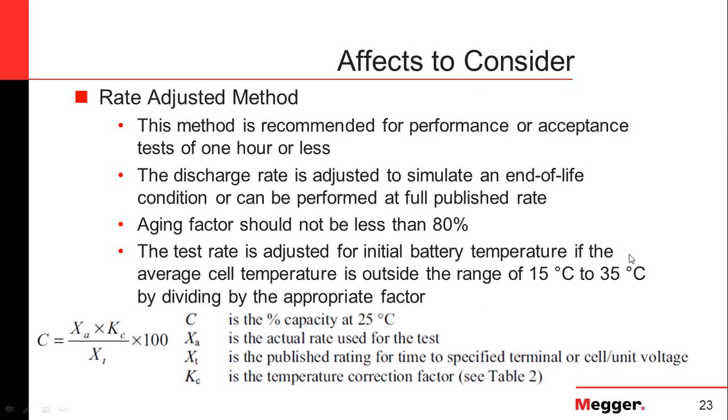The only other time you adjust the rate of current is if the temperature range is outside of 15 degrees Celsius to 35 degrees Celsius. As long as it's within there, you don't do anything else with the rate, the test current rate.